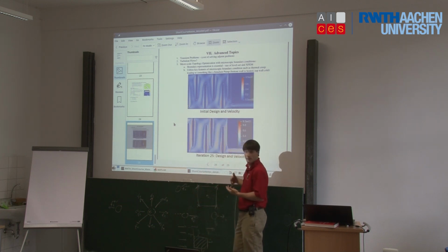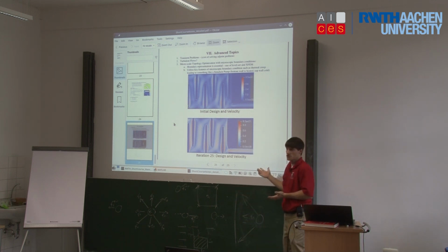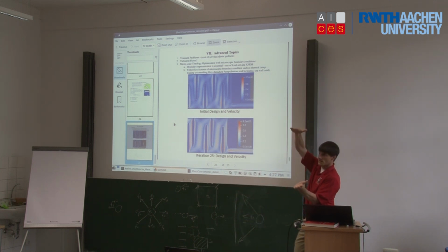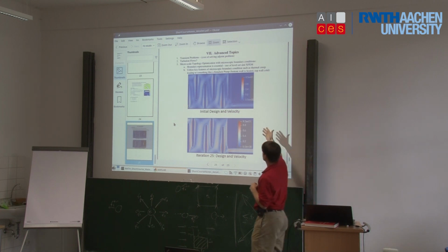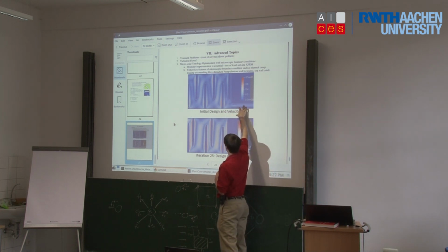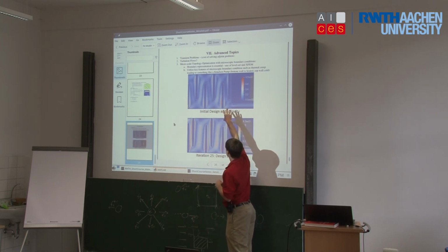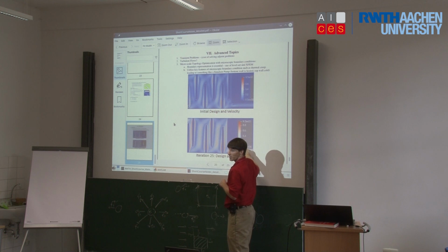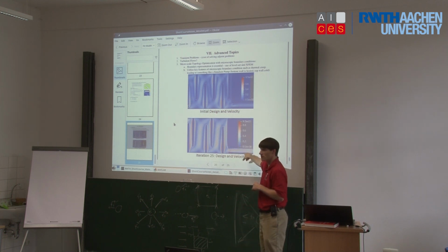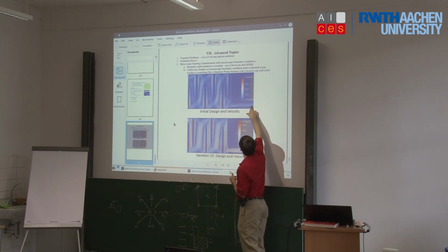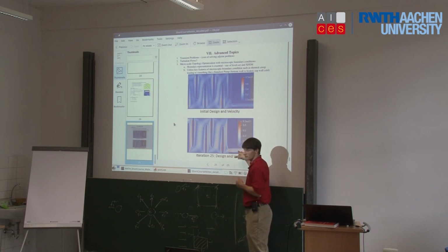You can actually pump fluid through these channels just by applying a temperature at the bottom and the top, a low temperature at the top, a high temperature at the bottom. And so this optimization now said, well, if we start with this, what would be the optimal arrangement of these fins in order to get the largest amount of fluid flow through this channel down here? And so you can kind of see here the velocities are low, here the velocities are fairly high through the outlet.